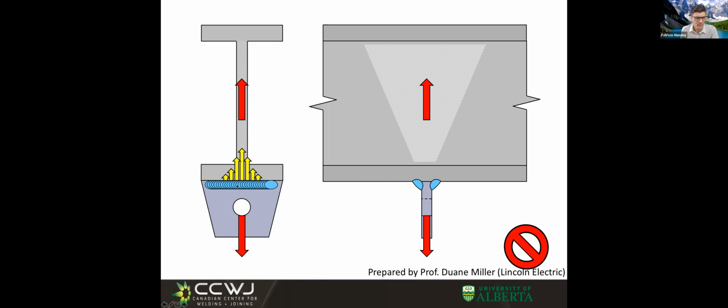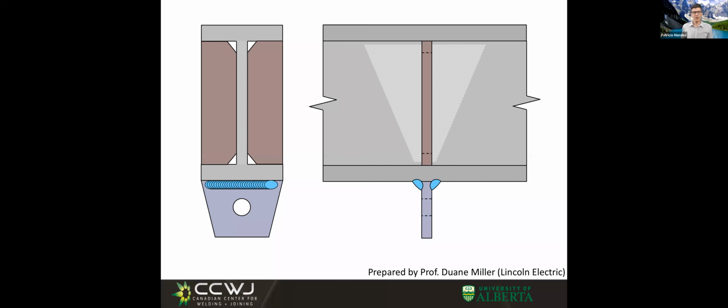So what happens, and this is exactly what you would see if you do finite elements, is that these parts that are more compliant take less load. They take less load because whatever load is going here gets relieved by the bending of the flange. What is against the web? No, that is very stiff. So don't do that. But what can you do?